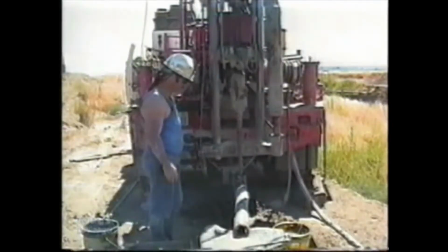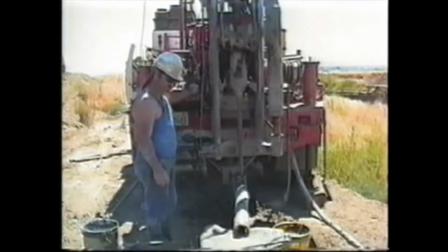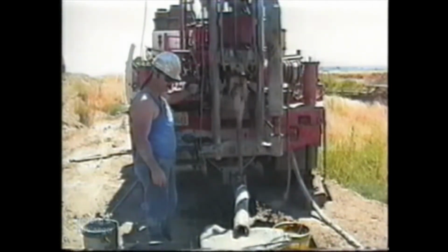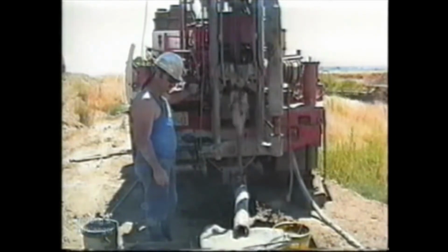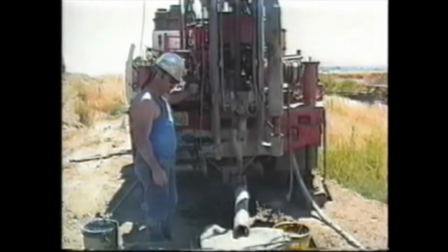It is recommended that the diameter of the borehole be 4 to 5 inches. As the diameter of a borehole is decreased, the penetration resistance is likely to increase. Side discharge bits should be used when rotary drilling, because the jetting action of a face discharge bit disturbs the soil at the bottom of the borehole. Most drill bits can be modified to be side discharging by spot welding on baffles to deflect the drilling mud